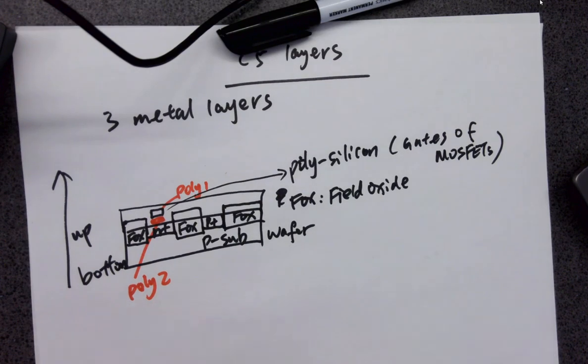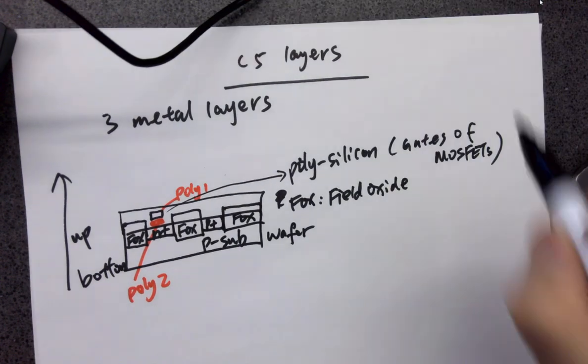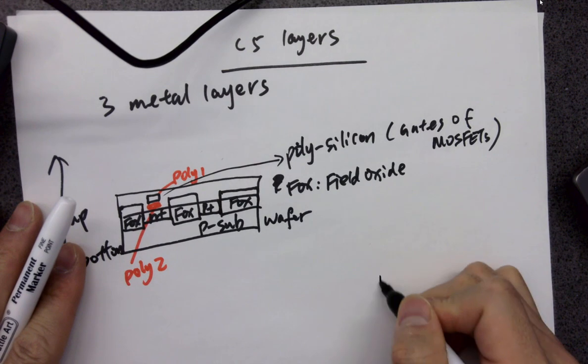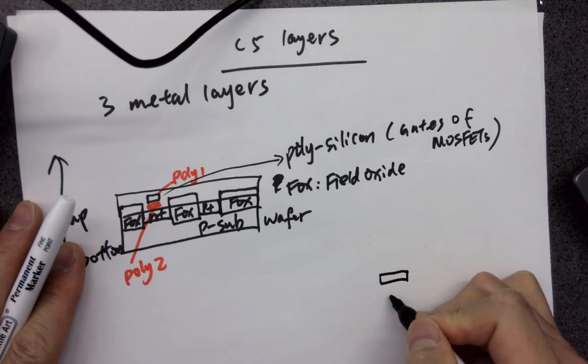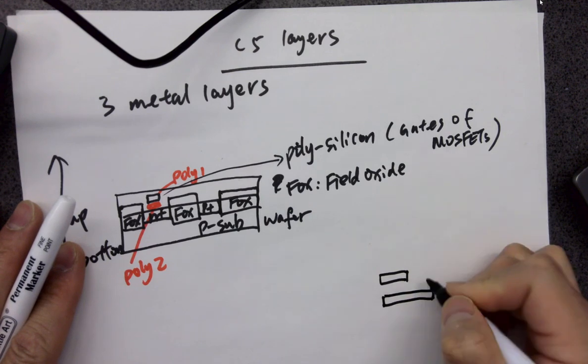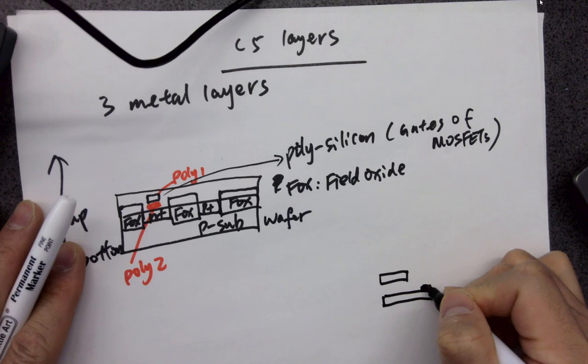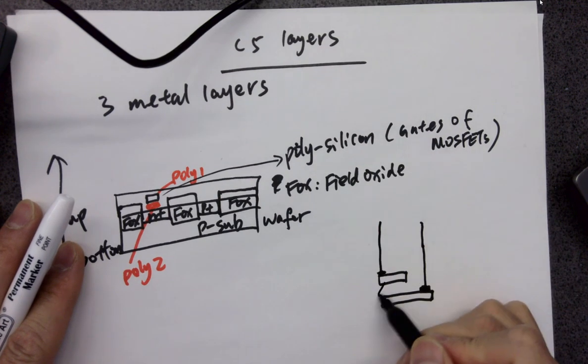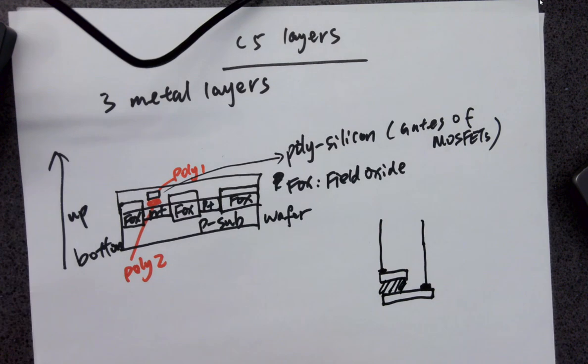It's really interesting. I'm going to draw the figures later, but you know how to draw a capacitor in your layout. So you got a poly 1 here, okay, and you have a poly 2 as well. And here's your metal. You draw a metal wire, another metal wire. So this overlapping area forms a cap. That's usually how we design the capacitor in the chip. Okay, that's how that works.